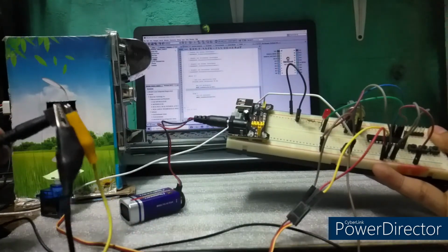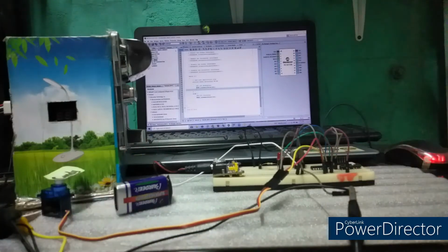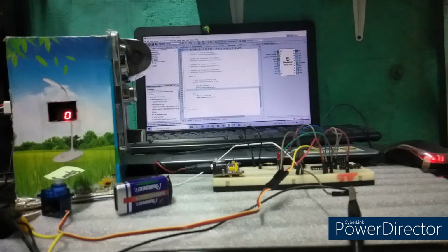And after that, we will be connecting a 9 volts battery to our power module, and then these alligator clips are used to connect our DC jack to our 12 volts power supply, which will power our 12 volts coin acceptor. So now, we will be connecting our positive 12 volts here to power up our coin acceptor. As you can see, our coin acceptor is already powered up.